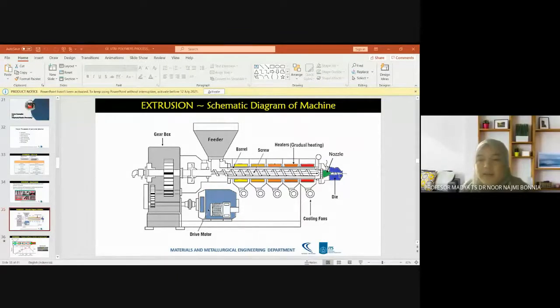In multiple thin film processing, which involves deposition of polymeric membranes along with other material, which is metal oxide, if the polymer used has a low melting temperature but was used as the bottom layer, is there still a way to anneal the film at high temperature?